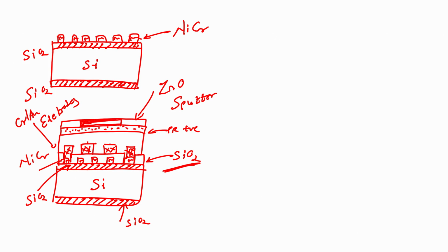We only want to protect the photoresist over the electrodes and not on the contact area. So, we only want to protect the zinc oxide on the electrodes and not on the contact area of the electrodes. So, we have this bright field mask, right. This is zinc oxide here, all right, and this is our bright field mask.